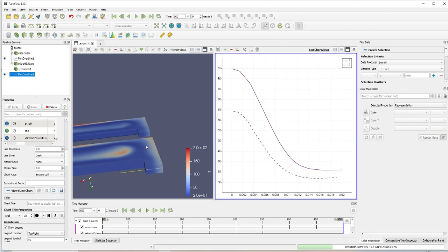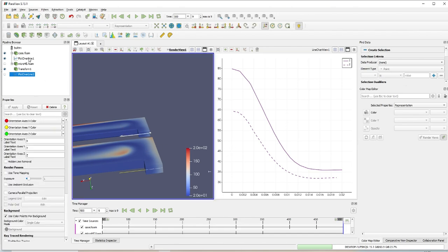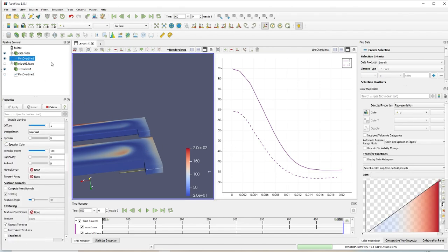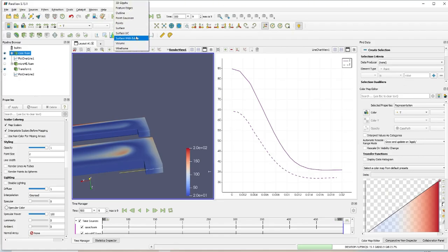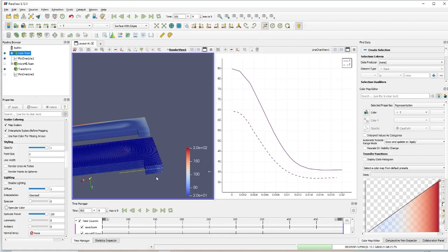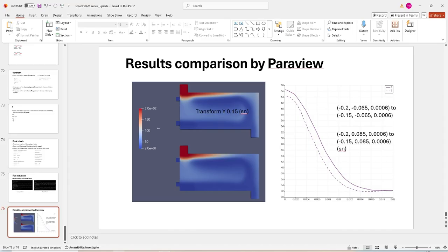But anyway, you can always change the mesh, here. So if you change the mesh by introducing more refined regions along the wall boundaries, you might have a better solution compared to the current one.